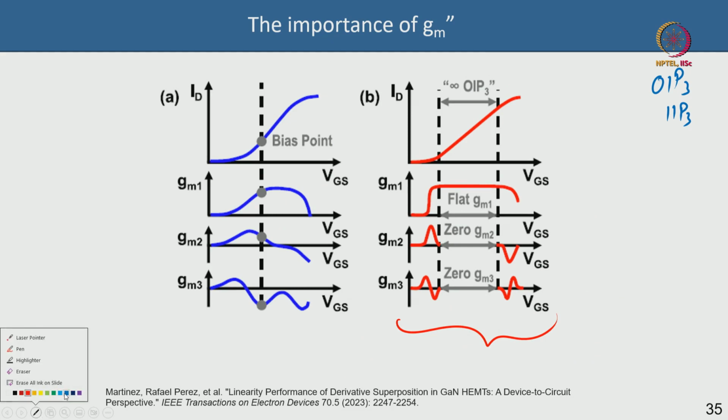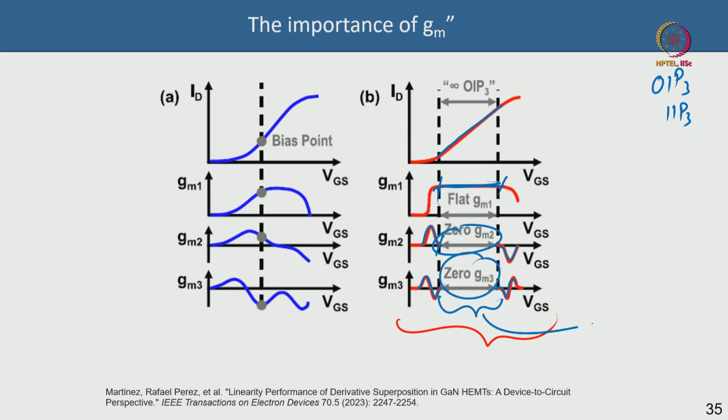You can see that this is as linear as possible, and if it is as linear as possible, then you get a gain which is flat, and then the first derivative will look like that, the second derivative will look like that, but because this was flat, that is why this is 0 and this is 0. So within this range your double derivative of GM is 0, which is fantastic, it is great.